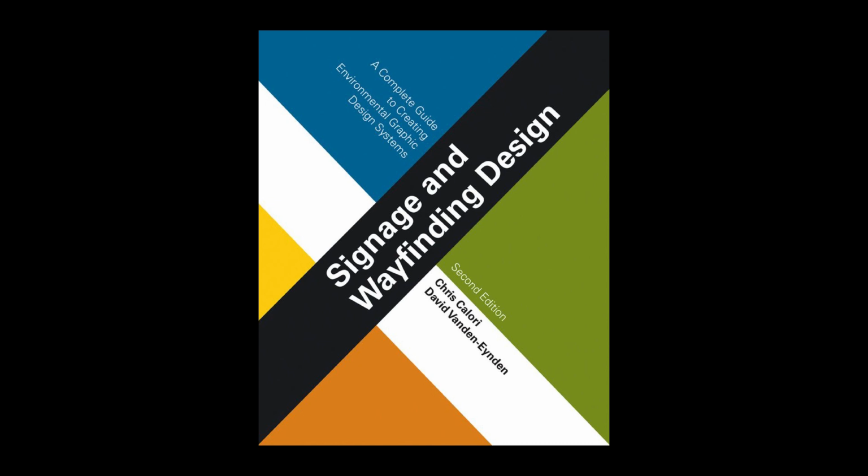Two other important tips about the detail and formality of the technical specs. Unless all the specs are treated as drawing notes, there should be as little redundancy as possible between any drawing notes and the letter-sized spec document. There will always be some redundancy between the two, but it's time-consuming to indicate a spec twice or to need to change a spec in two places rather than one.